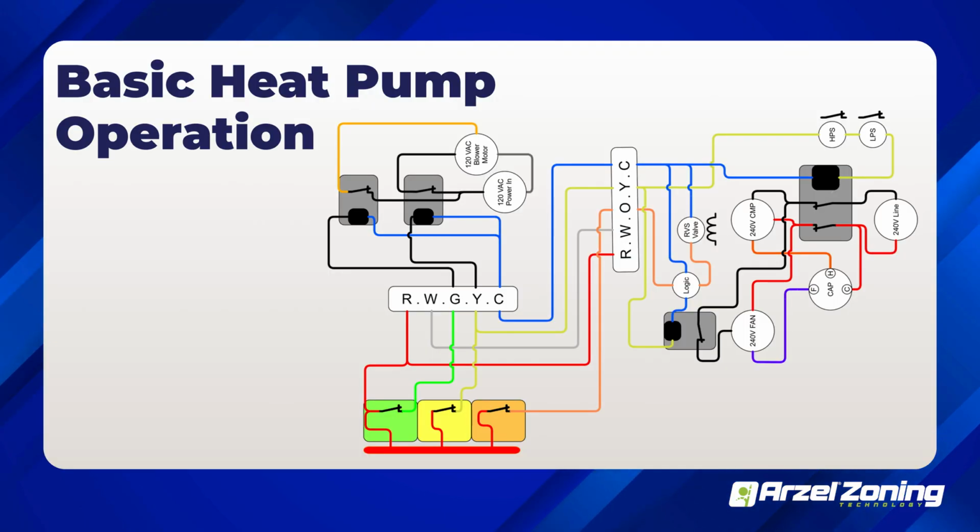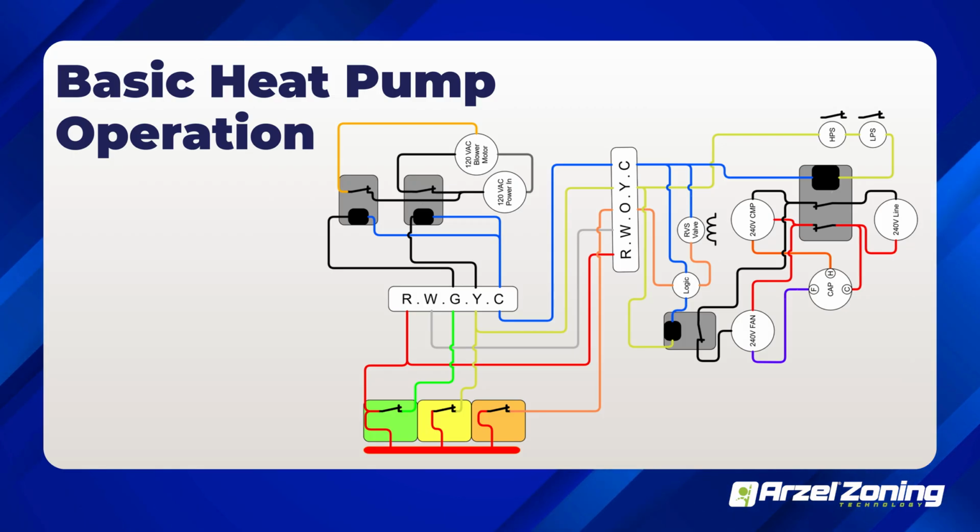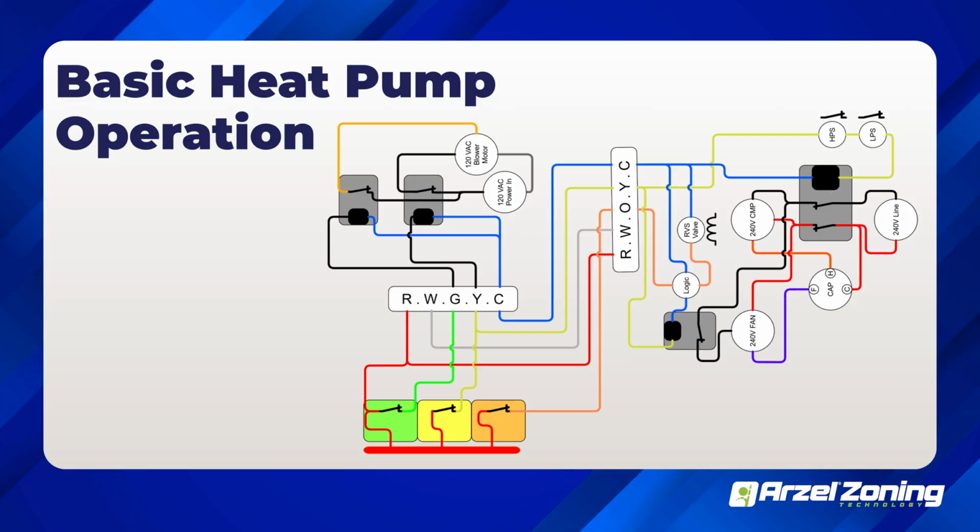A heat pump adds an additional layer because there's a defrost board outside. Once upon a time, the defrost board would throw me for a loop, but then as I became more and more familiar with how low voltage circuits worked, the defrost board really isn't any big deal, because it's all about a low voltage source controlling a high voltage source.